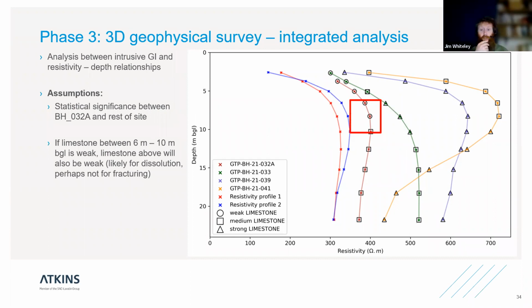Something I should have mentioned is that the groundwater table, we believe for this site, is well below the 20 meters that we're looking into the ground. So we're kind of removing groundwater as one of the assumptions that we would normally make about the ground. So we're assuming that the variation in resistivity here is either associated with perched water, or it's to do with the change in clay content or fracturing of the solution states. There's still several things that we're possibly indicating as the cause of our change of resistivity.